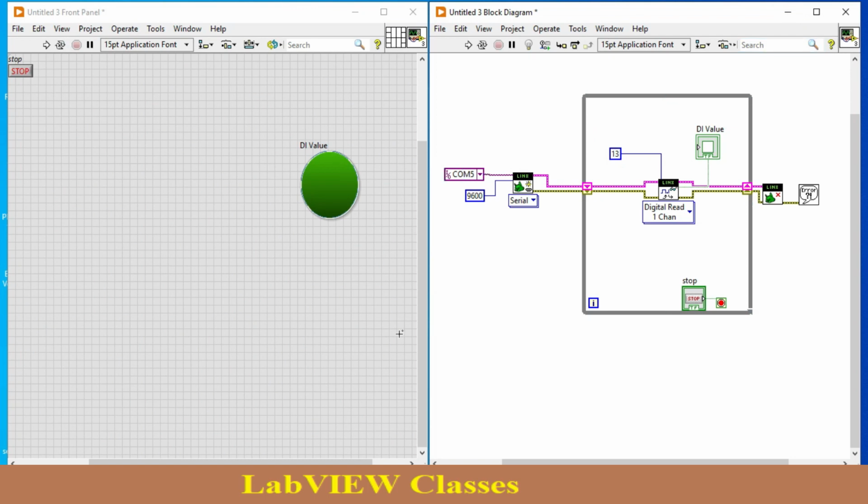Is it visible to you? Right now, I just take a single wire. I connect one end to the 5 volt that is available on the Arduino board. Okay. I connect the other end to pin number 13. Five volt to 13. It's a pull up. Okay.